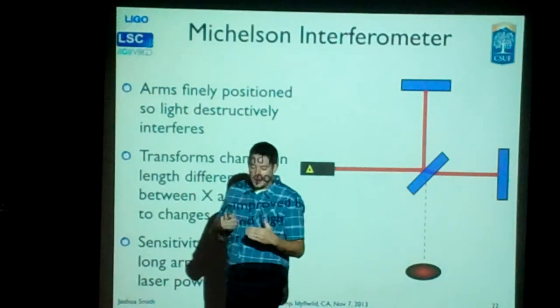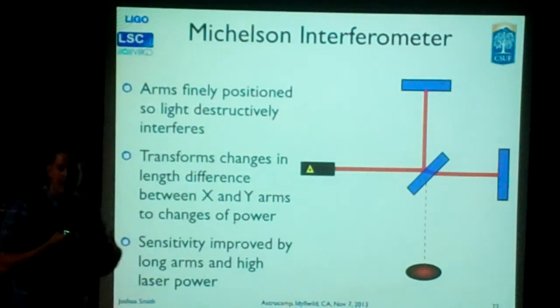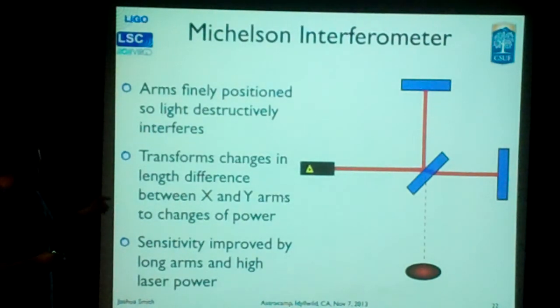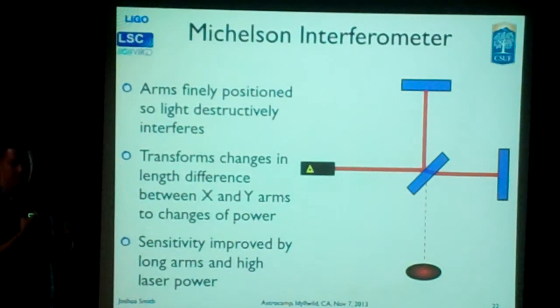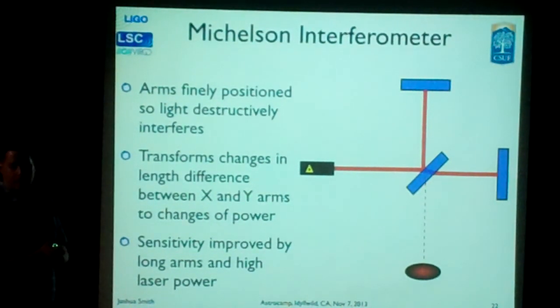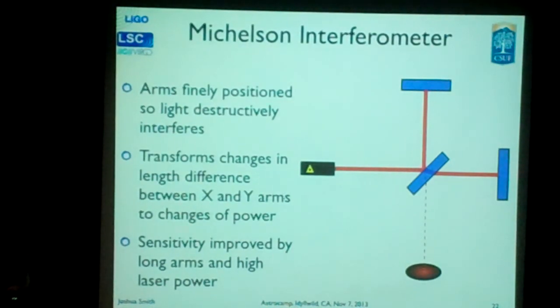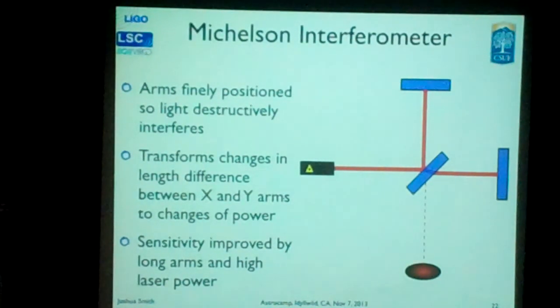And so we hold it in its exact right position all the time with feedback control, and then, to be honest, rather than measuring what comes on the photodiode as our signal, we measure what we have to push on the feedback as our signal. So we have to hold everything exactly in its linear operating point and measure what pushes we do to see the things. And that gets rid of the big macro changes, so if you have a signal that's small, you would see that. Yes, so we have many tiers of forces that we apply.